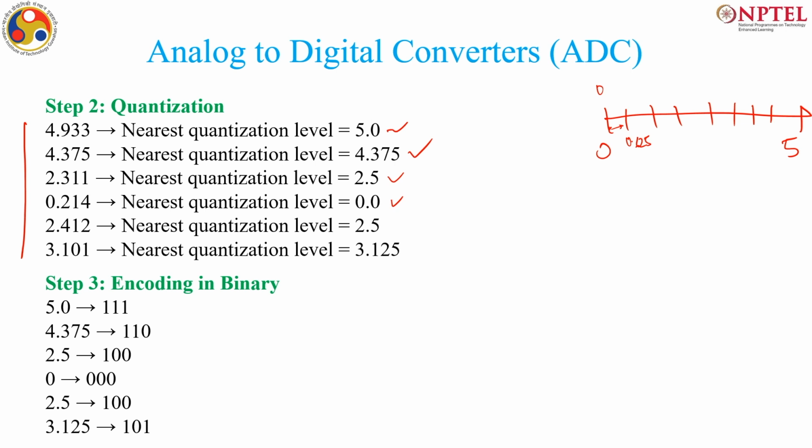If you use a 4-bit quantizer, then it will be 16 possible values. So, more the bits you are using, the finer approximation you are doing to the analog signal.